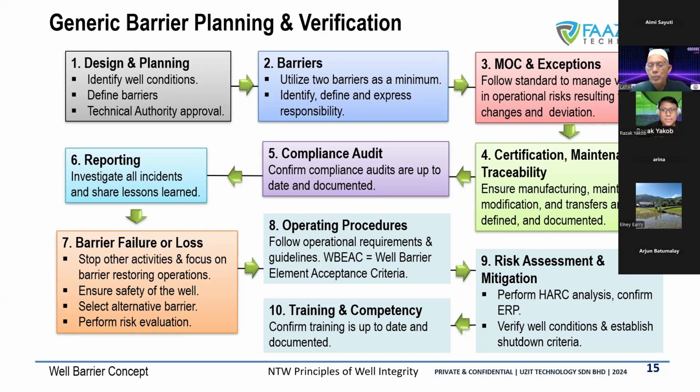If you are drilling open hole, suddenly you have losses. Of course, you lost the hydrostatic head. So when you lost your static head, you still have casing to protect you, and you have your BOP. So you still have the barrier that will be able to be used as your well control system, control the well, and go back to your normal barrier. So it's about three barriers when we drill a well, something like that.